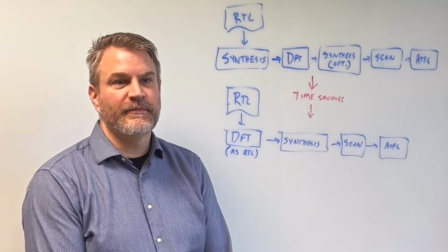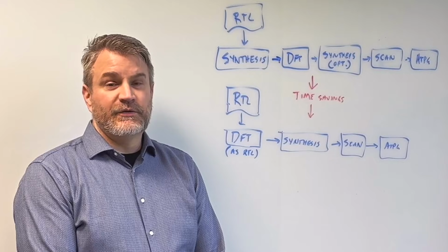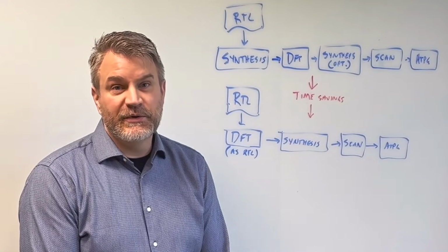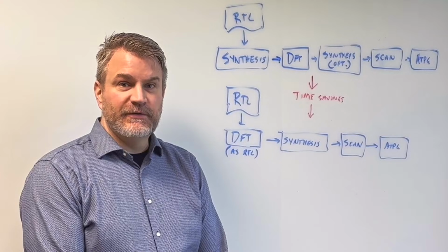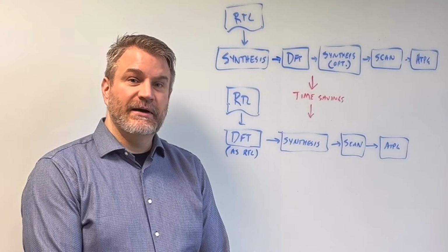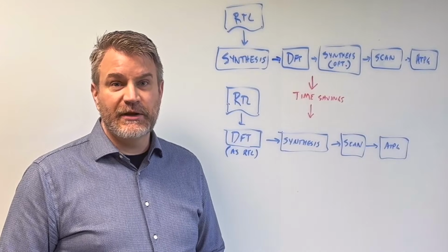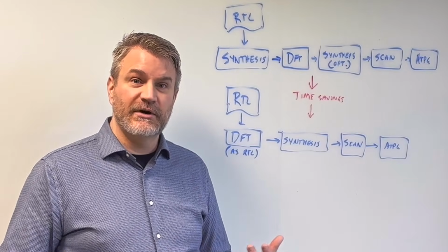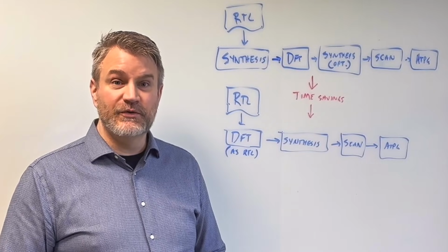As these designs become more complex, how do you account for all that with DFT? So one of the features that we developed for RTL test point insertion is the ability to identify areas of the RTL that are overly complicated, that have really long constructs or potentially uneditable syntax for the tools.